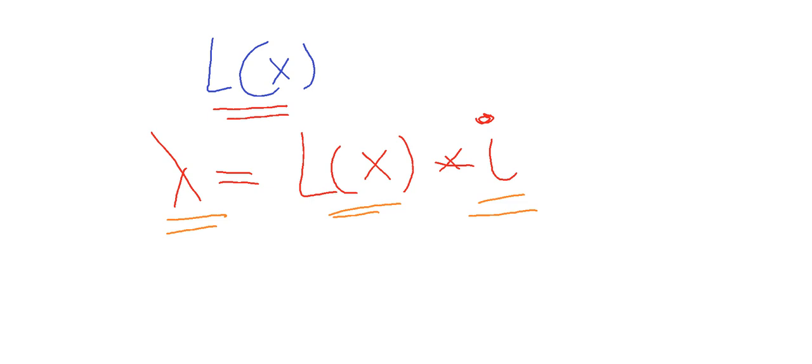According to Faraday's law, as the flux linkage changes, the EMF induced in the coil also changes, and this change in the EMF induces another magnetic field of opposing effect, meaning it will be opposing the movement of the plunger. This change can be expressed in a mathematical model that will be shown next.